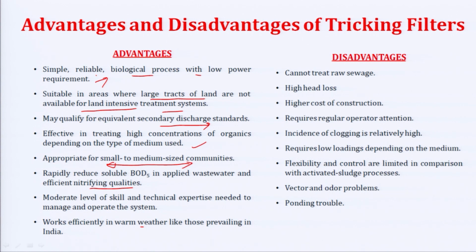But in cold places, imagine the filtering media left in the open in trickling filters. It may get very cold and the filtering media may get frozen, which means the bacteria will die. So, a trickling filter is not going to work in those cases, or if you want it to work, you may have to heat up the whole environment.